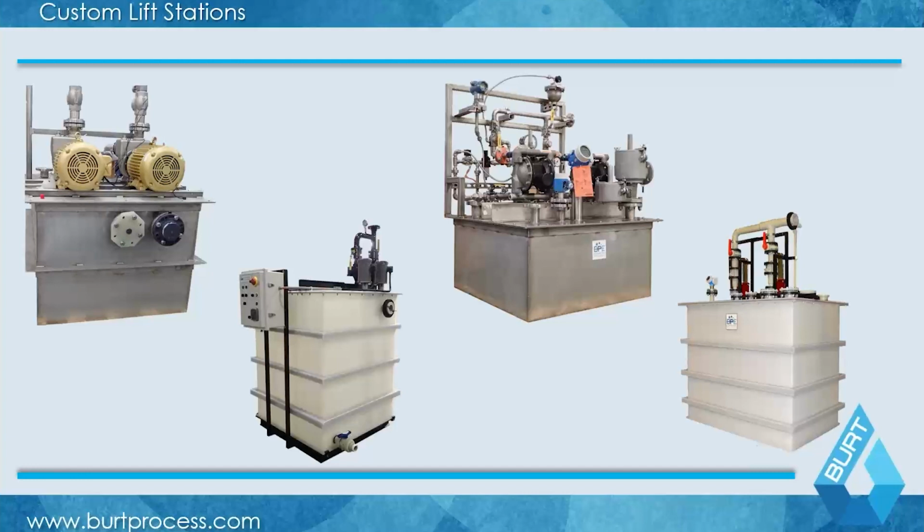Lift stations aren't necessarily designed based on a residency time like a pH system, like a CSDR. They are designed more on basically not short cycling the pumps. So if you have a peristaltic pump that can run dry, you can make the station very small in those cases. But typically 3 to 5 minutes is fairly consistent to minimize pump cycling. But it does depend. There are a lot of different pump styles. You can see here stainless steel self-primers, the bearing pumps, the AOD pumps that can be utilized as part of a lift station. Again, specific to what you're pumping, and what your flow rate is coming into your system.